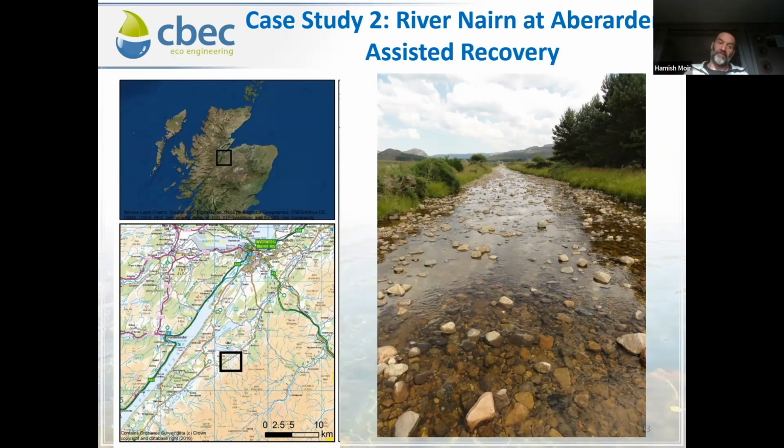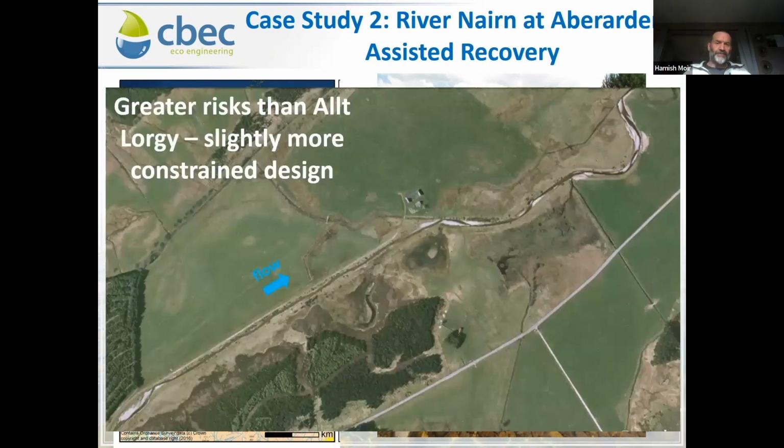And when it does flood, it creates very significant flooding issues, but also under normal flows, all the agriculture adjacent to the channel, the drainage was impaired because the drainage ditches couldn't drain into the river that was just too high in elevation. So the idea here, here's the straightened section, it's over 1 kilometre long, was to design a more sinuous channel. It's a little bit of an initial conditions design, because we've got to give it this proto channel to work on, but we've really just dropped the river into this new orientation and let it evolve over time.